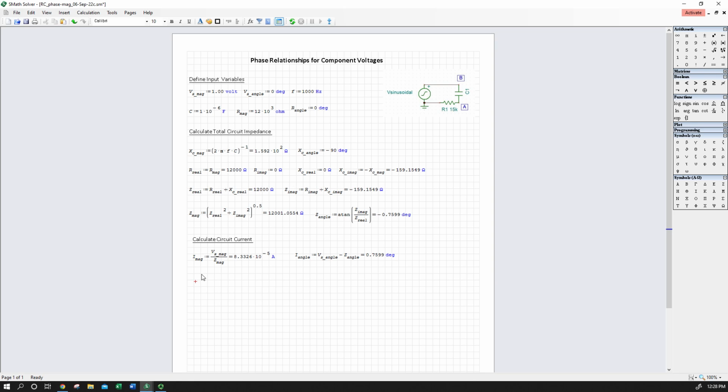And it is legitimate to use the term impedance to indicate either a pure resistance, a capacitive or inductive reactance, or a blend. So impedance kind of is a good term to use if you're really not sure what it is, or if you want a grab bag to just say something that resists current flow, whether it's by storing energy in a capacitor, in an electric field, storing energy in a magnetic field in an inductor, or just turning it into heat in a resistor. It impedes current flow. That's why it's called impedance. So we could denote our pure resistance as our resistive impedance if we want.